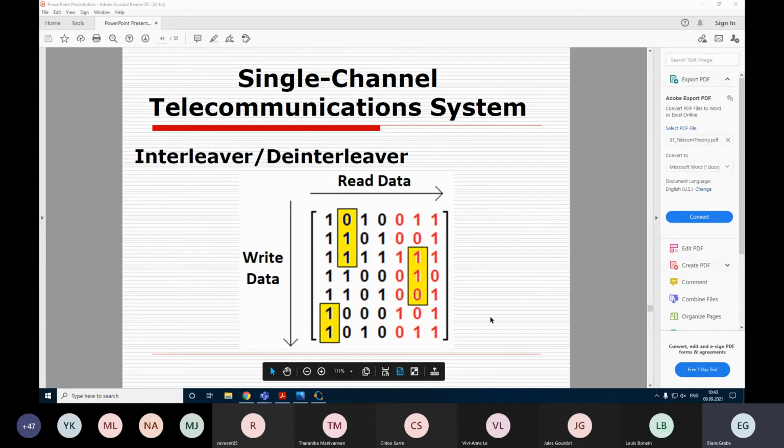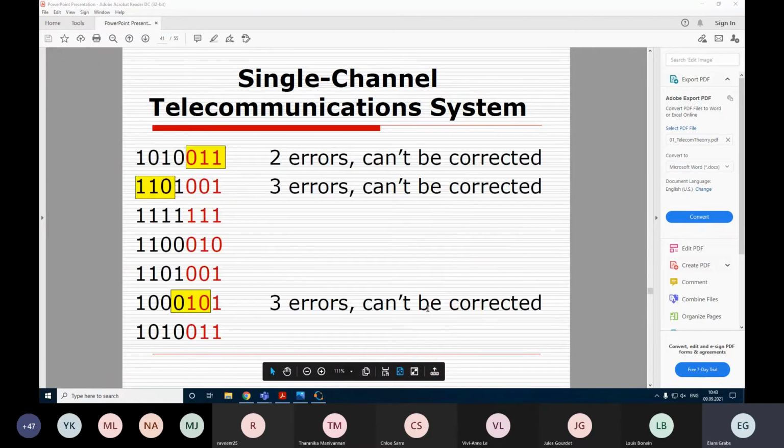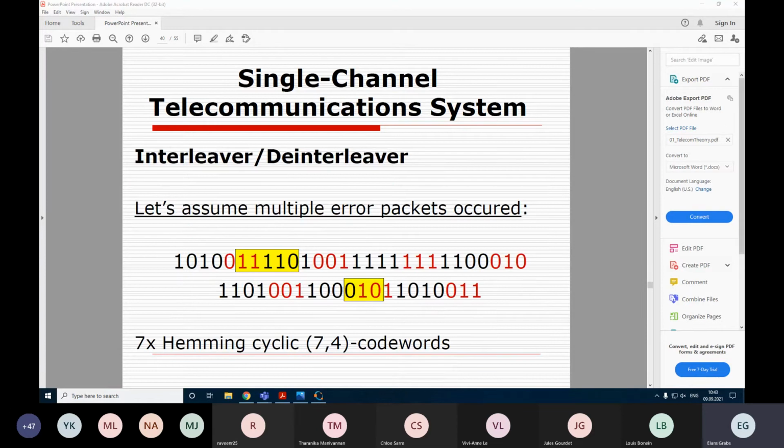This shows that interleaving can help spread the packet error into separate independent errors and use a simpler code, because otherwise we would need much stronger codes, which are called Reed Solomon codes, which are capable of correcting entire bytes. Reed Solomon codes work not with binary data, but with bytes.